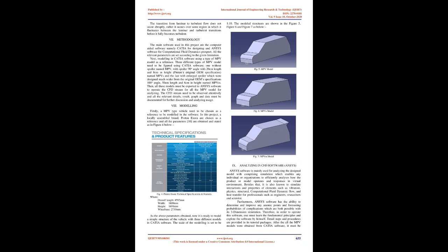More sophisticated drag measuring tools named drag balances use flexible beams fitted with strain gauges to calculate the drag electronically. Besides that, it can be calculated using the formula, equation 1, as shown below. D equals 1/2 rho V squared CD A. Where CD equals coefficient of drag, rho equals density of air in kg/m3, and A equals frontal area in m2.